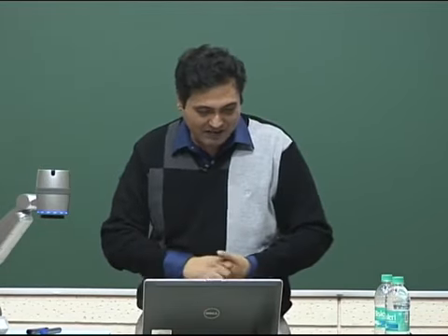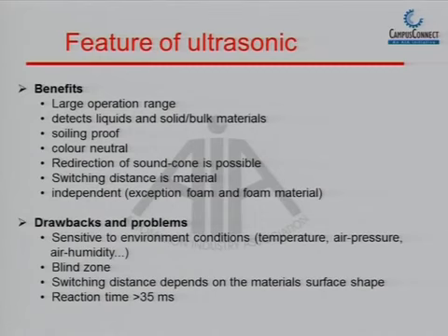These are some of the drawbacks if we talk about them. Temperature and humidity. With change in temperature, the sound waves change. We all know ultrasonic sensors are working on the principle of sound, that means the sound waves are reflected back from the target. We know the frequency, we know the velocity of sound, that is 344 meters per second, that is the speed of the sound, and the time taken for the sound to travel and come back. So, based on that we calculate the distance, right.